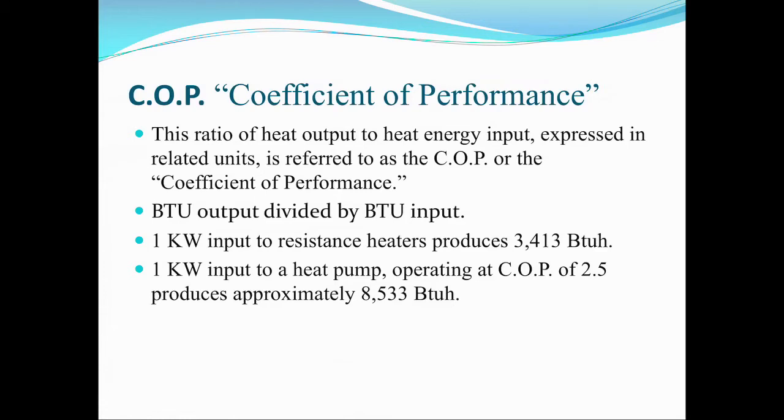And of course, the input can be converted into BTUs. Input's always going to be electrical energy, and we can convert that electrical energy input into BTUs by looking at how many kilowatts of energy a person uses to create that heat, and you can multiply those kWs times a factor of 3,413 BTUs, which is the conversion for kilowatts of energy to BTUs.